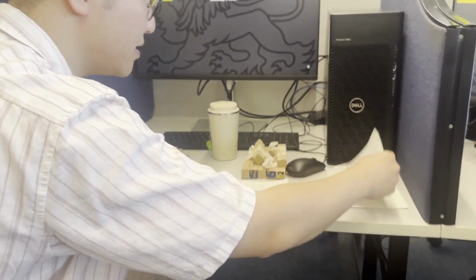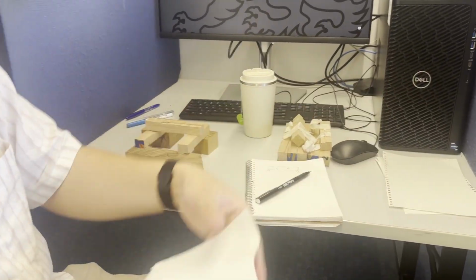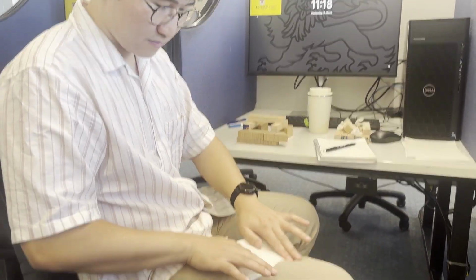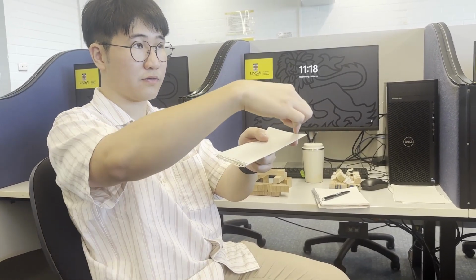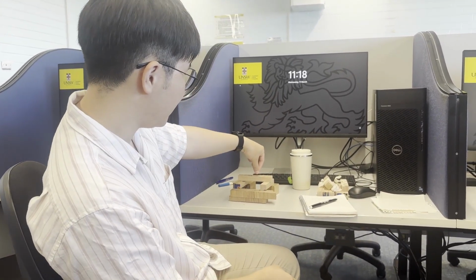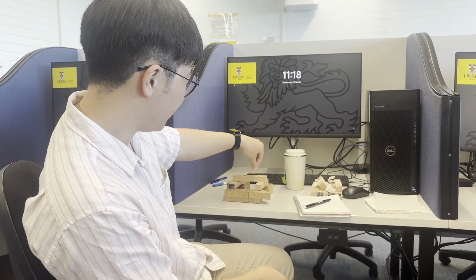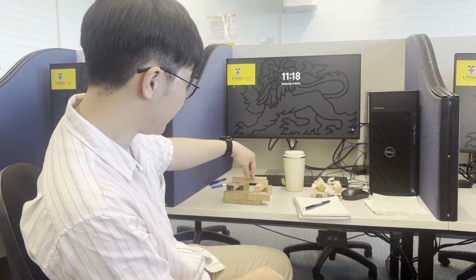By the way, something that's pinned, this took me a while to realize when I was first starting at my job. Something that's pinned basically allows rotation. You see the self weight of this paper is sagging it like that. I've got my 2 fingers here, and even though these aren't literal pins, if this is loaded, it freely allows rotation here, and it's supporting it vertically. That's something that's pinned. You can't really see rotation in it, but this is a pin support because it rotates about here and here.